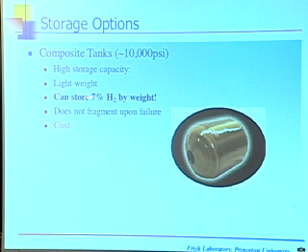Already, they're storing something like 7% hydrogen by weight. That is, we have a lot of pressure and a low mass on the tank material, so it goes way up there. So we have high storage capacity. We have lightweight. This tank, unlike a steel tank, will not fragment upon failure. If the tank fails, it's very clever. The polyethylene insert powders, which is really good news on two fronts. First of all, it takes a lot of energy to break all the polyethylene down to a powder, so the whole shock wave doesn't get out of the tank. And the second is you're not going to have some fragment shooting through the passenger compartment of the car next to you and taking out whoever.